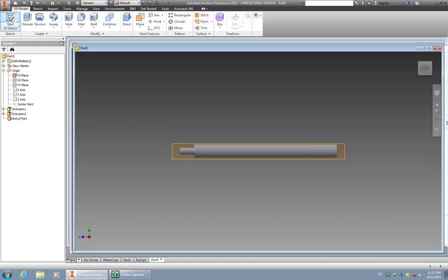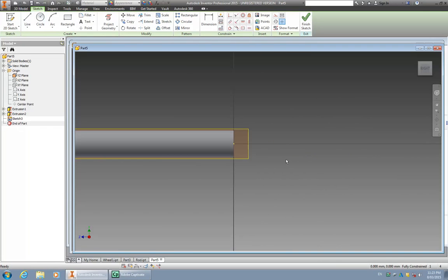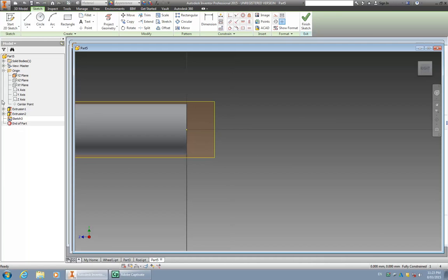So I'm going to start a 2D sketch and then go onto the plane, highlight the plane, and it's now coming into focus. So I'm going to make it a little bit larger and choose to do a rectangle. This time I'm going to use a 2-point rectangle from each vertex, draw it out and change these lengths. Now I want the radius to be 5 because I'm going to rotate that around to create a 10mm pin, and this dimension over here I wanted to poke out 20mm. If you recall, that was what we planned.